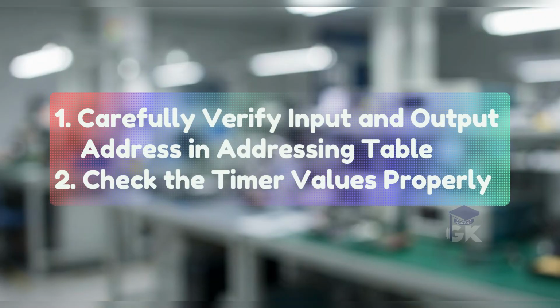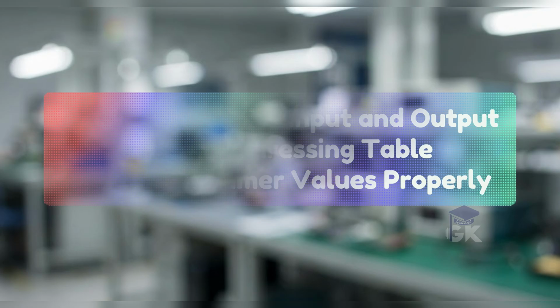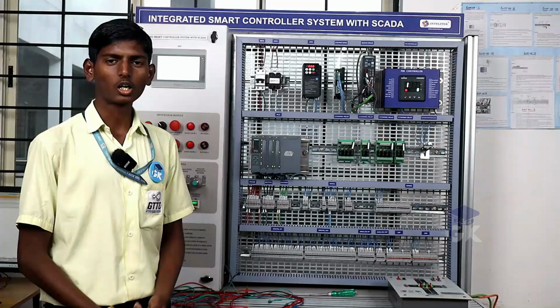Before using the trainer kit, carefully check the input and output addresses in the addressing table. Also ensure that the timers are set with the correct time values. Now, let's perform this experiment practically on the trainer kit and observe how it works.